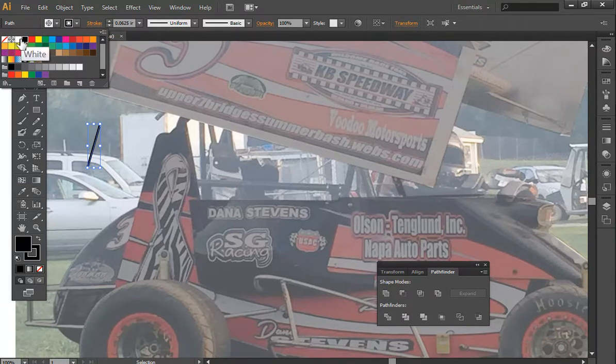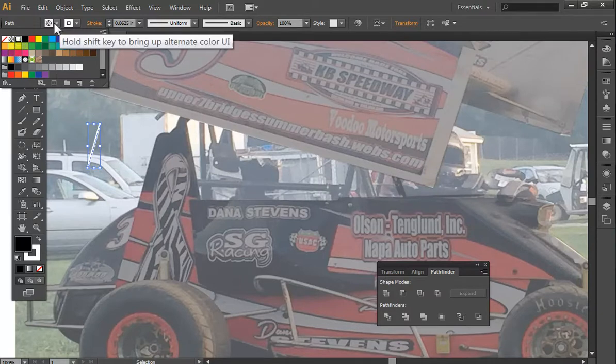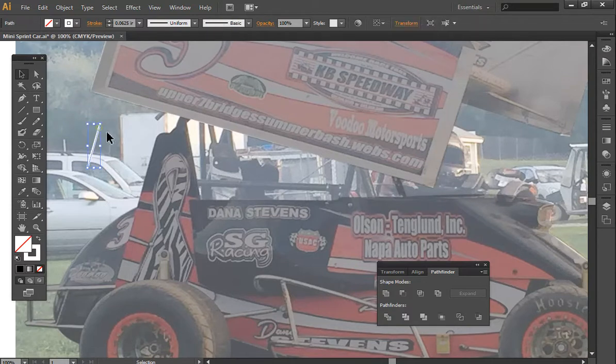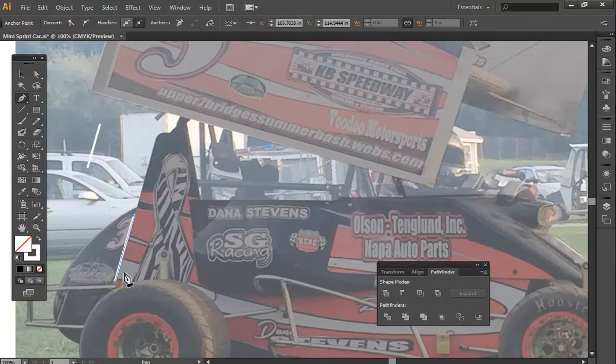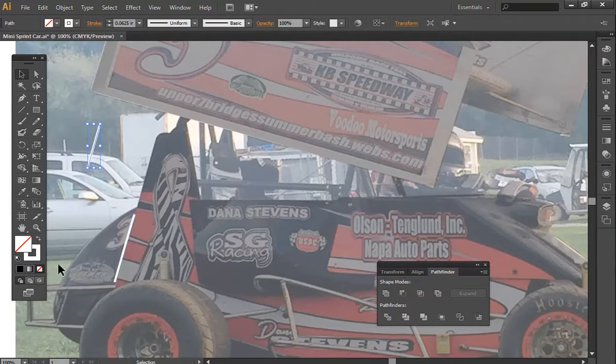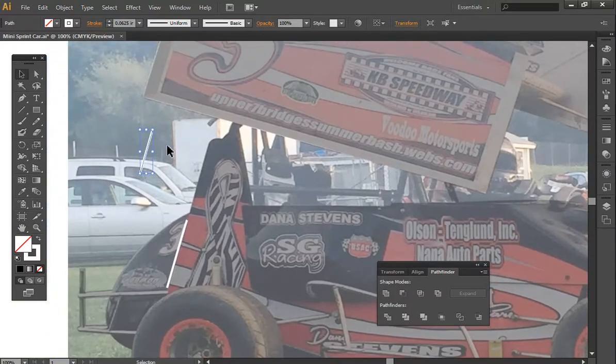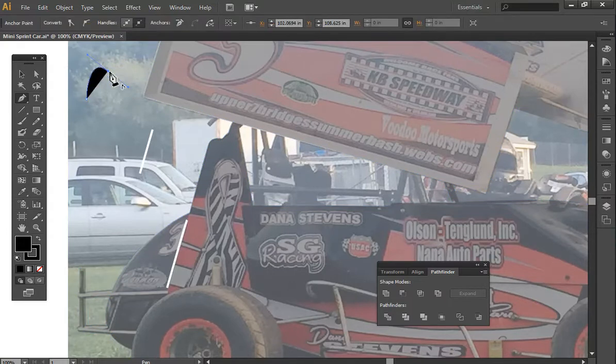What I'm going to do is change the color of that line to white. Let's do that. Okay. And then we're going to take out the fill color. We don't want any fill color in there. So anytime you click on this and click on the pen tool, you can go and set your node points, and it'll pre-program it with the information associated with this line. In Illustrator, if you select any entity, it's going to preload all that information up here of what that is. So if you use the pen tool again, it's going to use the same values.